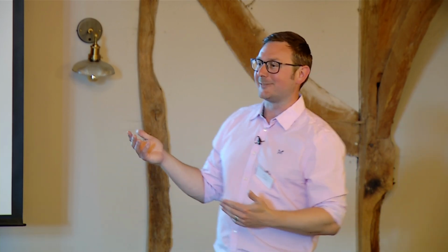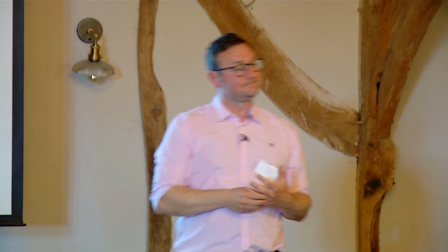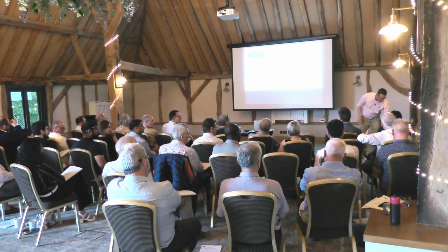So I have had instances like that. I think it's factor and degree. Say regulations are black and white, and I prove another example when they're not. But on a first floor room, if there's any possibility of it being utilised as a habitable room, then the second floor becomes an inner room, and then it's not permissible.